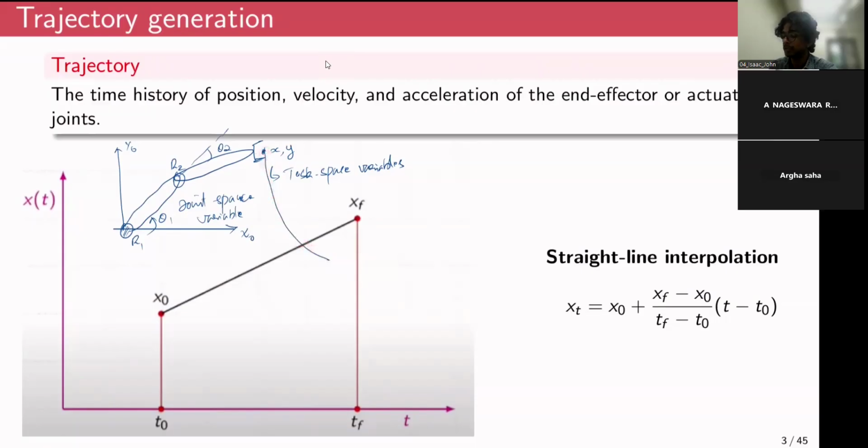So using some trajectory planner, you will generate a stream of intermediate positions and velocities. And then using inverse kinematics, you will obtain the corresponding joint variables, theta1 as a function of time, theta2 as a function of time. And that would be your inputs to the motors.